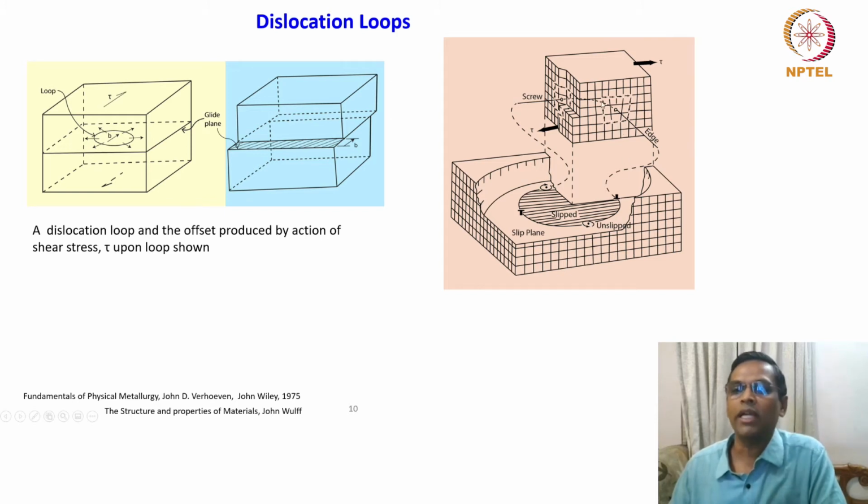And we have to make sure that, in terms of geometrical understanding, you just look at this clockwise Burgers circuit, which shows the Burgers vector B, right? B is here. This is B, and it should be the same Burgers vector on the other side also.